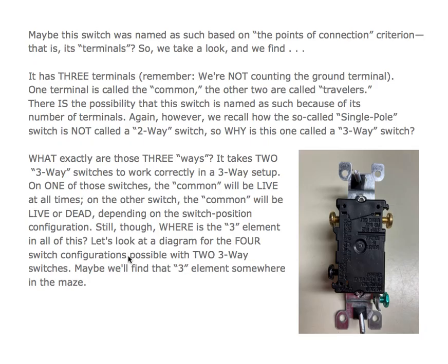So we take a look and we find it has 3 terminals. Remember, we're not counting the ground terminal. One terminal is called the common, that's this one. The other 2 are called travelers. Here's traveler 1, traveler 2. There is the possibility that this switch is named as such because of its number of terminals.